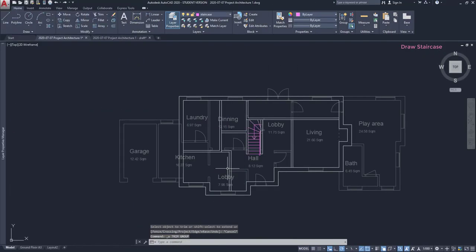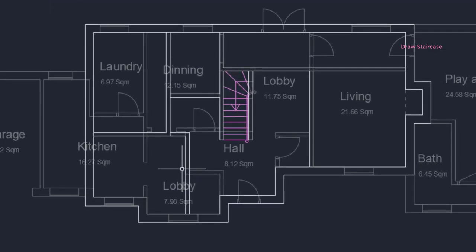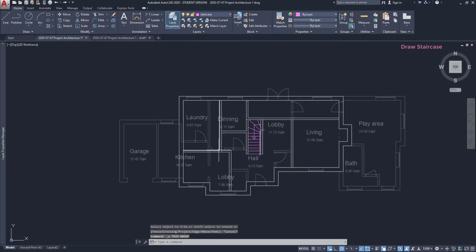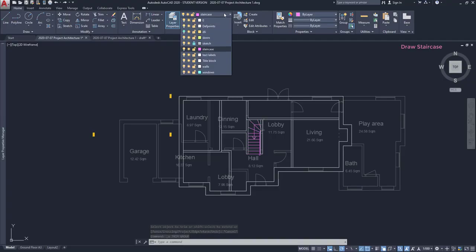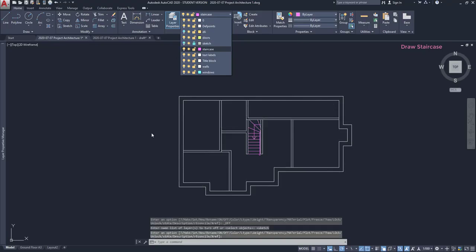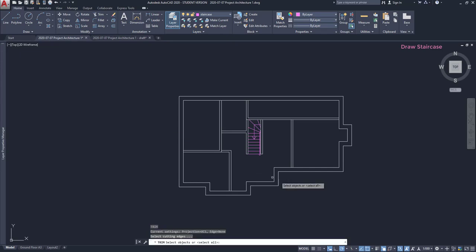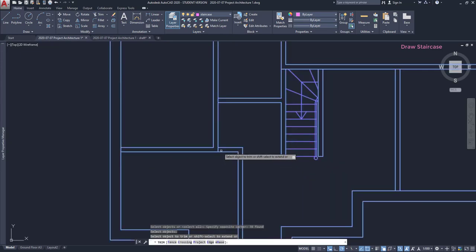Trim extra segments on the walls. After completing the internal walls, we realize there are some lines between walls to erase. First, I suggest to turn off the sketch for a few moments, as it's easier to view the plan. Then, use the command trim. Select all the floor plan, press enter, and click on those segments to erase.